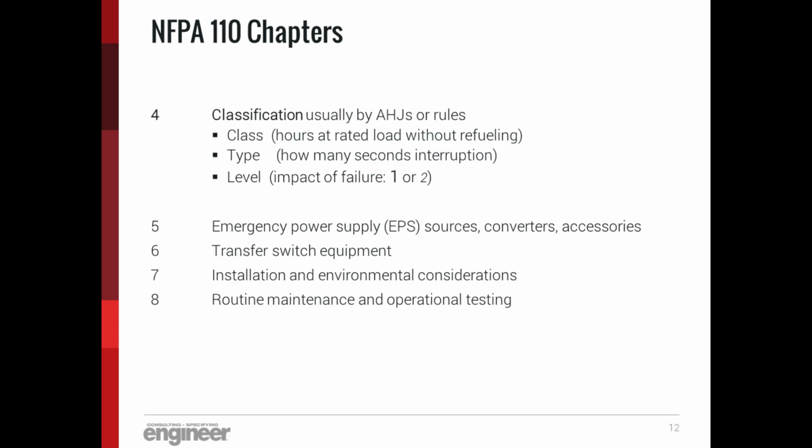Within the NFPA 110 chapters, basically chapter 4 is a very short chapter. It's the chapter that classifies the requirements. And the class is the hours at rated load without refueling. Now, presently in the 2010 edition of 110, there is a requirement for 96 hours, but not everywhere. It's only 96 hours in certain seismic zones.